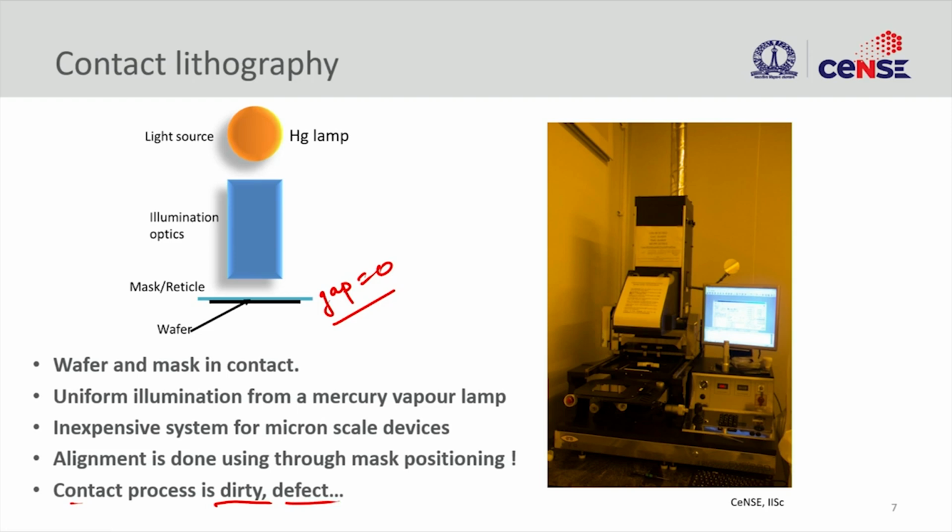So one should be careful about the cleanliness of your mask, and also what all the contamination you have on the wafer. So whenever you do contact lithography, make sure that you wash the mask thoroughly, so that you don't have any contaminants, and also you don't have any particles, because we are going to have hard contact.